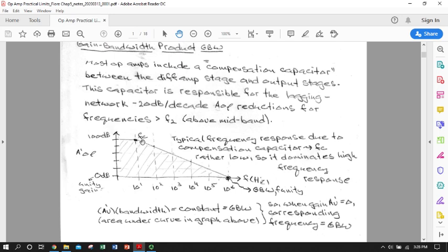And then our gain will roll down at 20 decibel per decade slope to a point where we have no gain. So it's a unity gain, 0 decibels, or V out over V in is 1. And so the frequency at which we reach 0 decibels is known as the unity frequency, F unity.